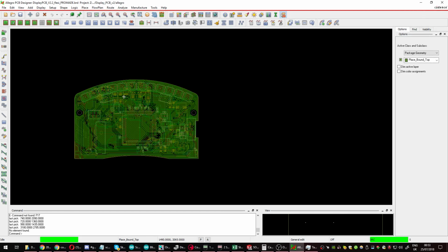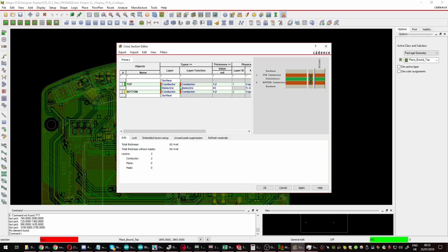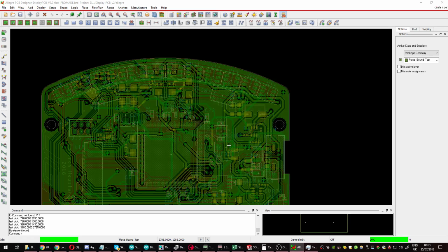So first off, I want you to check, just in case, that your dielectric is the right thickness, basically your board thickness. If you're making a normal PCB in university, or you're getting any normal expense PCB manufactured professionally, you're going to have 1.6mm thick FR4. That translates roughly to 63 mils, so enter that in and everything will be fine.